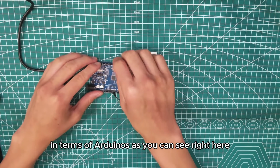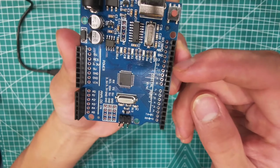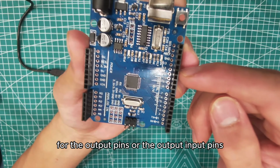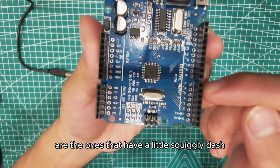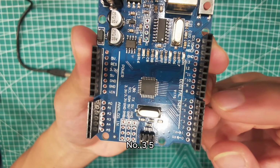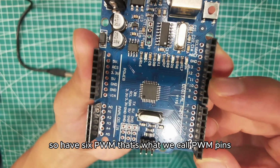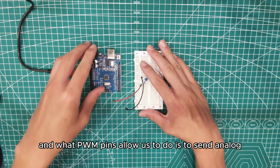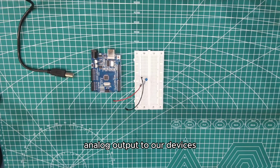In terms of Arduinos, as you can see right here, for the input output pins, the ones that are analog are the ones that have a little squiggly dash next to it. So here, number 3, 5, 6, 9, 10, 11. So we have 6 PWM pins. That's what we call PWM pins. And what PWM pins allow us to do is to send analog output to our devices.